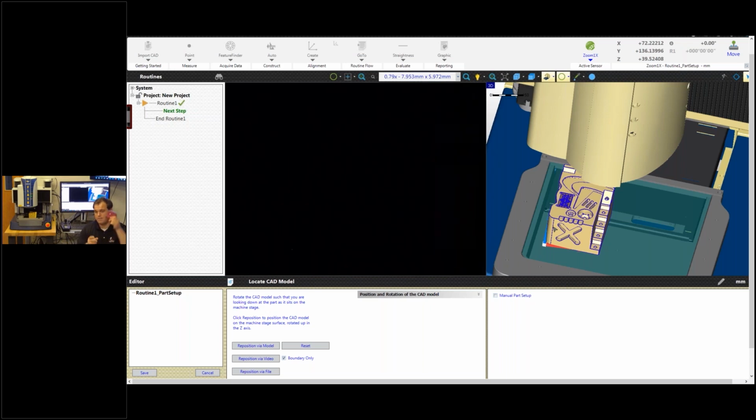For example, on this red part, I would probably have told you to find this lower left corner and focus on it with backlight and take a crosshair target and align it to that corner, and we would zero out X, Y, and Z in our DRO, our digital readout, and then drive over here and use this corner to set the skew of rotation for the part.